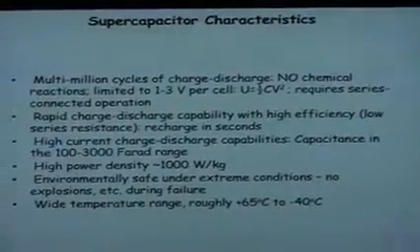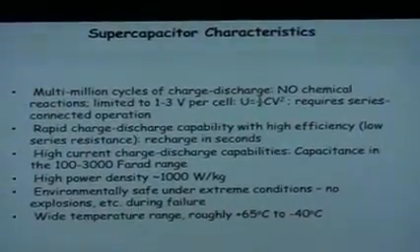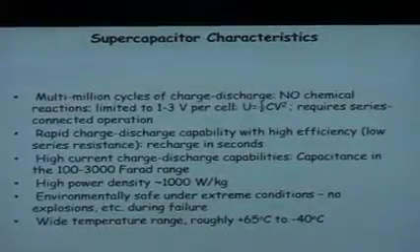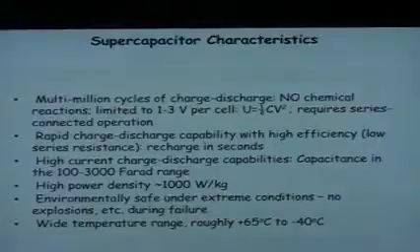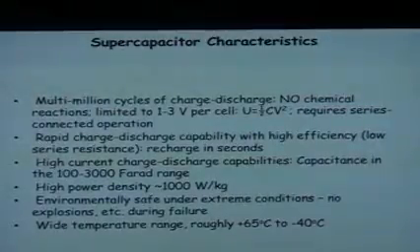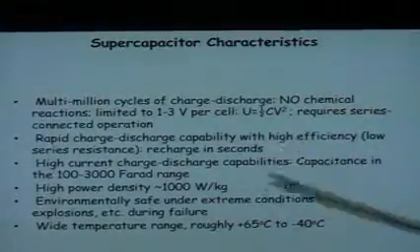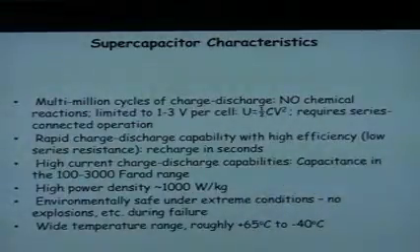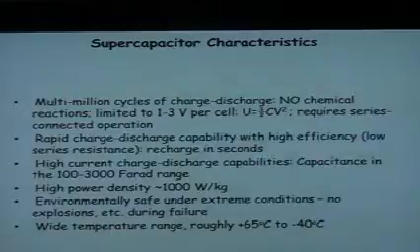The reason is that, in part, you make these supercapacitors very thin, and therefore they have low series resistance, and that low resistance allows for high rates. You can have this high power density, 1,000 watts per kilogram, order of magnitude.